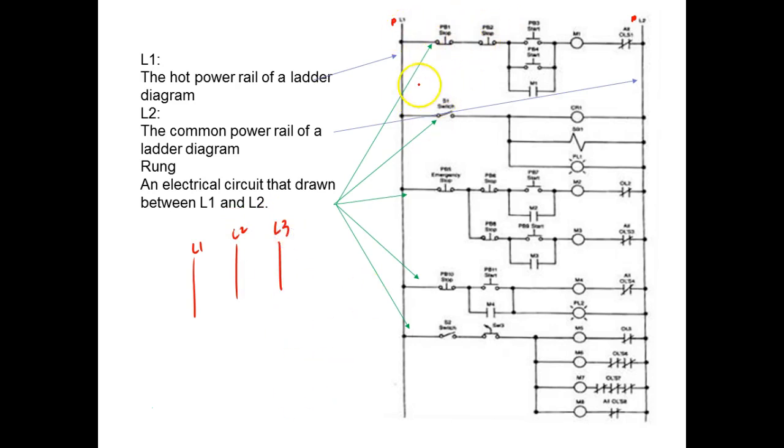This might be DC, and this might be 24 volts AC. If somebody doesn't know that, they take this L1 and hook it up right there, and you burn up your whole system, right? You understand? So normally in the controls they give it a little different name besides L1 and L2, but L1 and L2 is usually in the diagram. I call it PL1 and PL2 because that's what US Steel called it in their diagram.